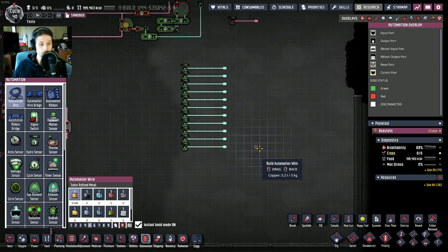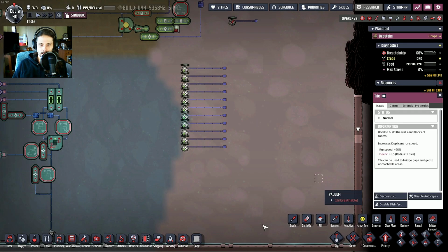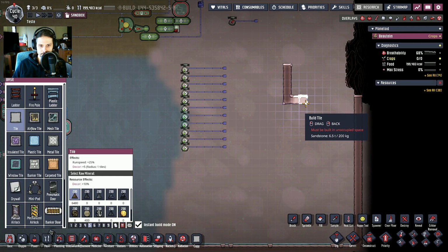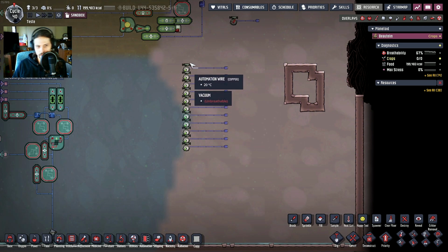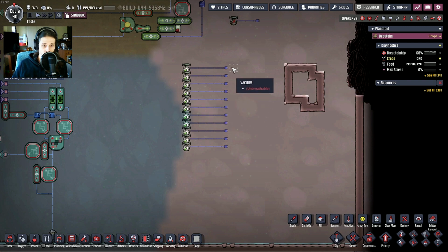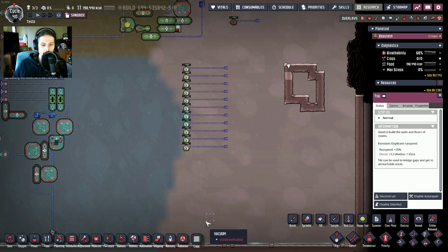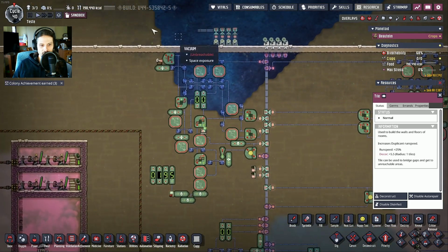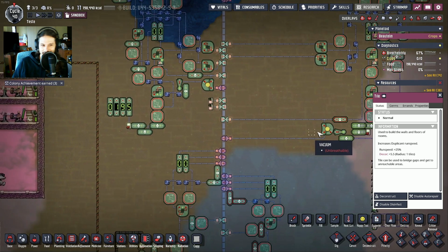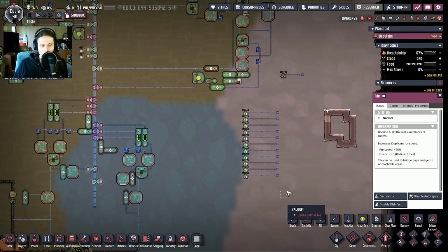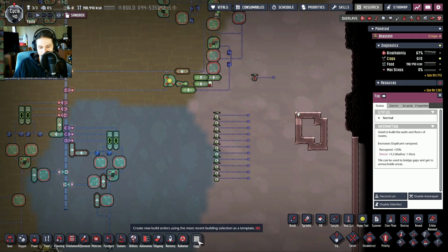the CAN bus system. What is this? Instead of having all of your sensors communicating directly to the ECU of your car, let's say this is the ECU over here, right? Instead of having all of these wires go from the engine bay and from the rest of your car, because you have other sensors, into the ECU, what you have instead is an encoder system. Similar to this one, but not really, much more complicated. This is a poor man's version. It's what I could come up with.